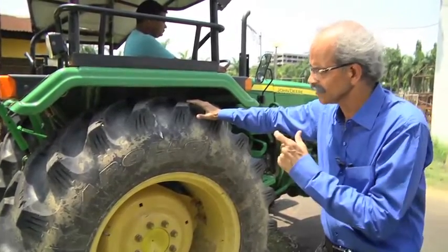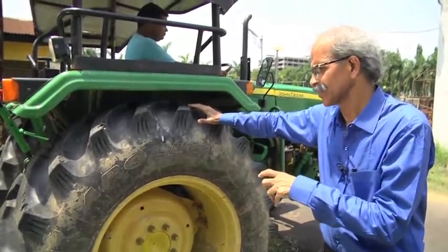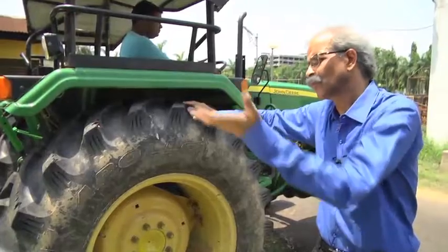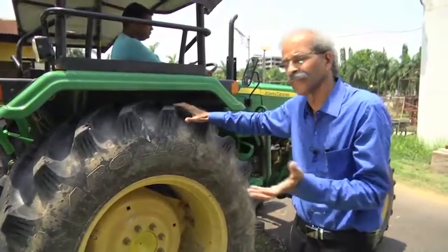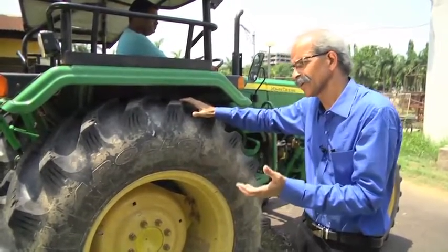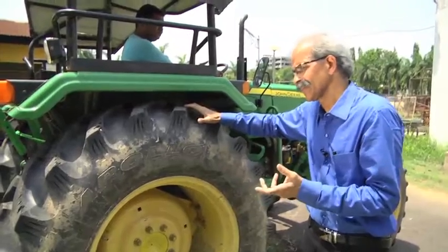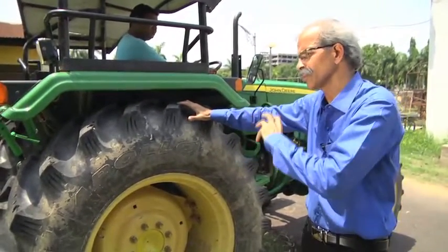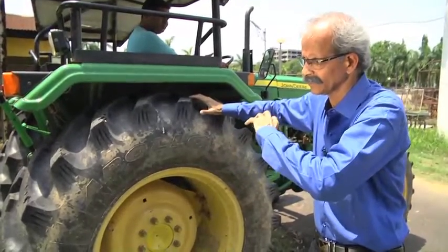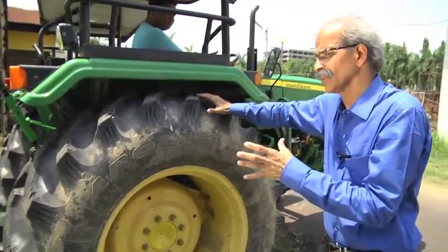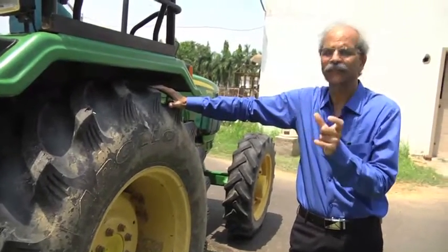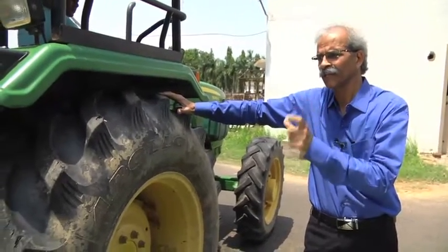Now, how much power we are taking from this tractor and how much power is actually required by the implement is still a mystery, because the soil is a viscoelastic medium, and that keeps on varying depending upon the soil moisture content, the depth at which it is operated, and the type of the soil. So, this is a complex thing which needs to be found out, and still people are working on the matching of the implements with respect to the power source. When we go into the mathematical treatment, I will show you how we are in a position to find out the matching implements for a particular power source.